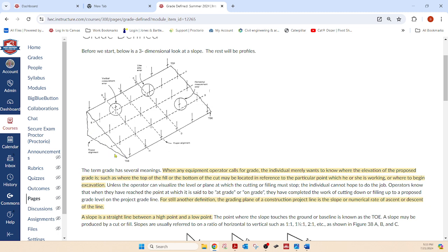Then he's going to come in here and move over 2 feet, and drop another 2 foot wide slab. So what you're going to have is a step up of 1 foot and then 2 foot level. It's going to continue doing that until he gets to this height right here.